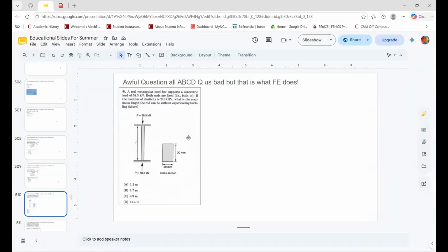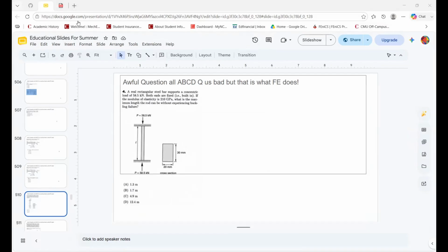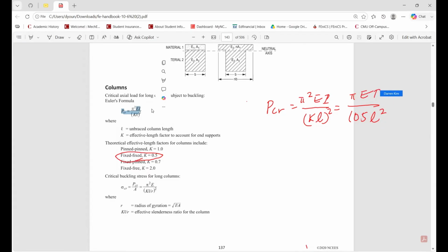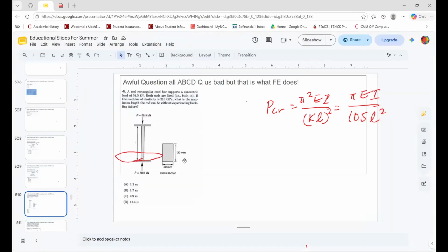So over here, does it give me the maximum stress, or what is it? It gives me P critical instead. Okay, that's fair. All right, we have to start by looking at the force over here. P critical equals pi squared EI over (KL) squared. We know that this is squared, by the way. Do not forget the square. That's really important for you guys to understand because I make that mistake all the time. With that being said, now we can figure out everything else over here.